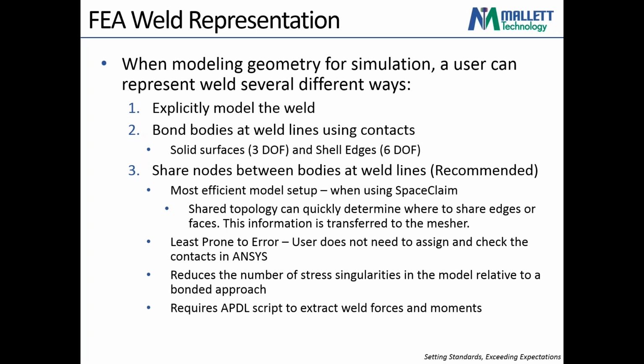Here we've had welded assemblies where we have hundreds, if not a little over 1,000. I think the most I've done is a little over 1,000 welds. In that case, I don't want to have 1,000 contacts in ANSYS that I have to define and double check, right? So it's much more safe from an error perspective and efficient to use the shared topology method.